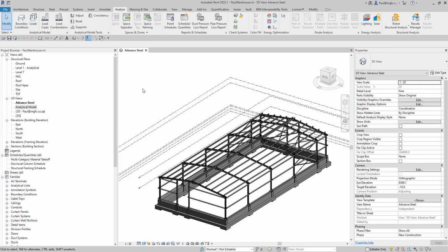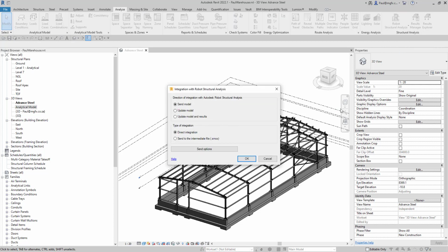Analyze tab. On the Analyze tab towards the right, you will find that you've got your Structural Analysis tab, the Results Manager, and the Results Explorer. Those are for you after you have brought a Robot model back into Revit. But the Structural Analysis drop down, Reinforcement Code Check, there's the one that we'll be looking at, the Robot Structural Analysis link. It's a pretty simple dialogue.